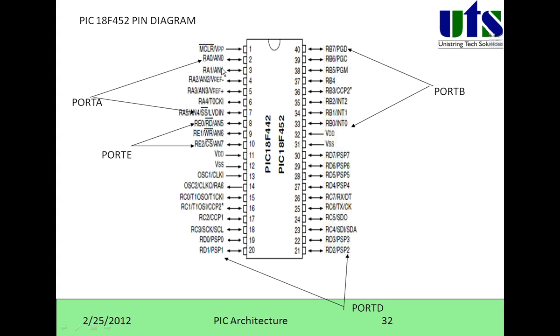Okay, it will be connected to the reset pin. Any application board will contain a reset switch, right? So the switch is connected to this pin. This will be low by default. Whenever you press that switch, it will go high. Then the complete data memory, the complete microcontroller, will be reset, and it starts executing again from the first, from the starting stage.